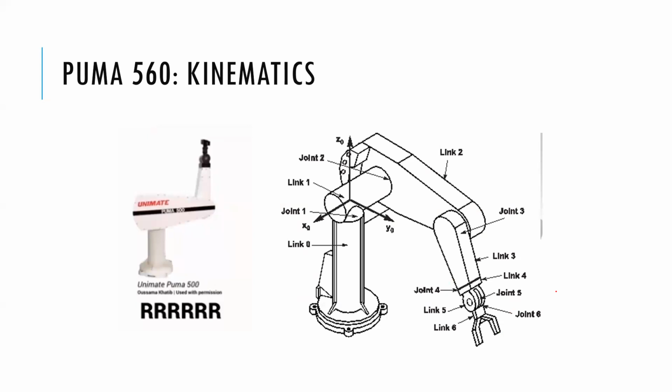So if you're designing your own system, or you're going to take a system out of the lab and you want to be able to program the kinematics, you just need to go back and measure the length of these joints, figure out how they rotate, and then do the dot product, and you'll get a 4x4 matrix out. It gets longer and longer if you do them symbolically. But if you actually have numbers in there, it's still going to be a 4x4, and then you'll be able to do the kinematics. I'm going to show you some Python examples.